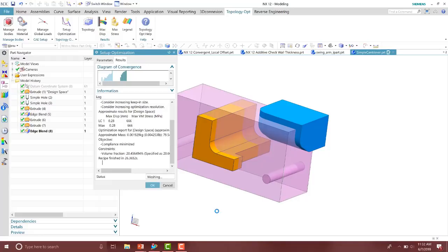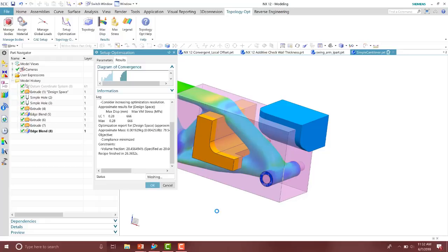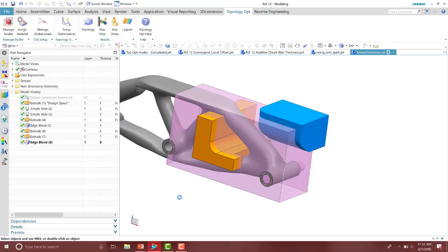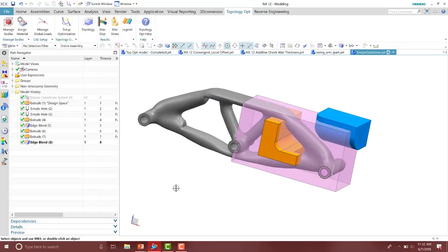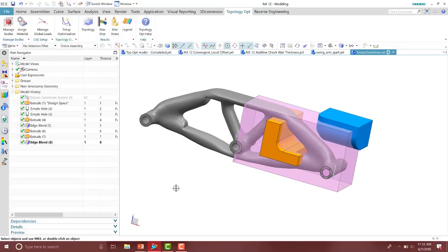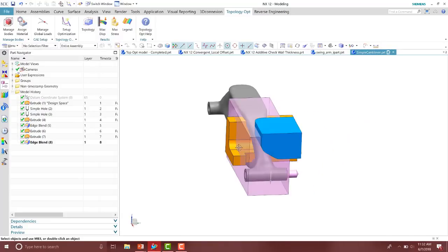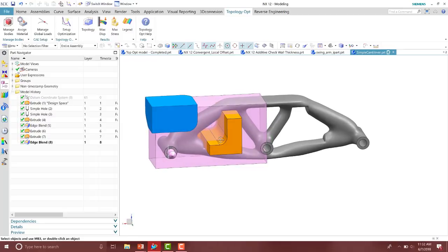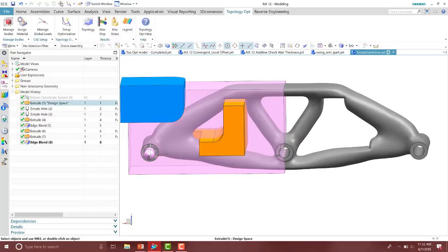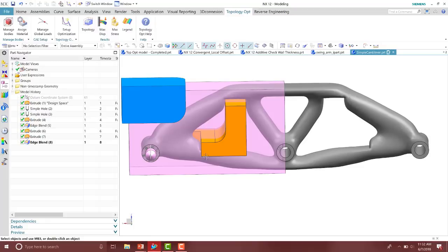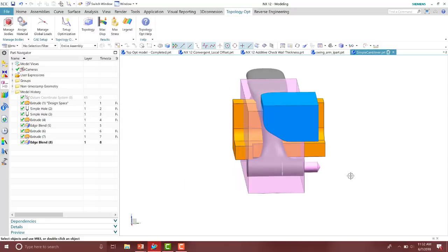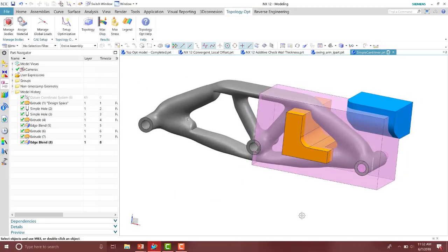that body. So the optimization is meshing here in the status, and now it says it's finished. So I'll go ahead and press OK on that. Now notice my body is symmetrical, so I only drew half of it, and then I have the bodies that are keep out areas. You could also specify an offset for that. Notice I have an offset in here of 0.5 millimeter. Okay, and then the pin. So notice I modeled the pin in there as well on the back side. So that's where it represents in my assembly.